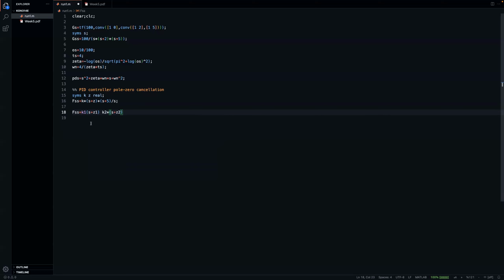If you look close to this, this part is the PI part, this part is the PD part, and a PID controller can be decomposed into its PI and PD parts. That's quite interesting to know, because one zero is here, the other one is here, and one pole at the origin is here, and you will have a PID-type controller. So knowing that can sometimes be very helpful, but let's go on.